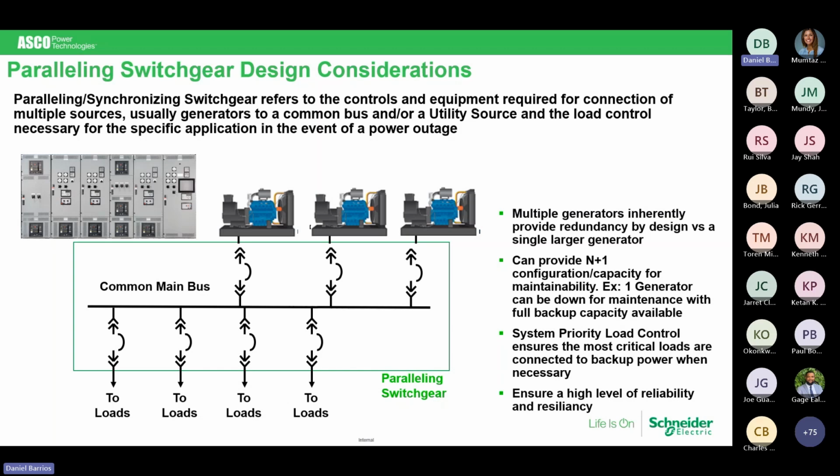The comment of an N+1 is that in your design, you need at least 2 of the generators online. You obviously have the third one for a bit of more redundancy, belts and suspenders, a greater capacity, maybe even for future growth or so.